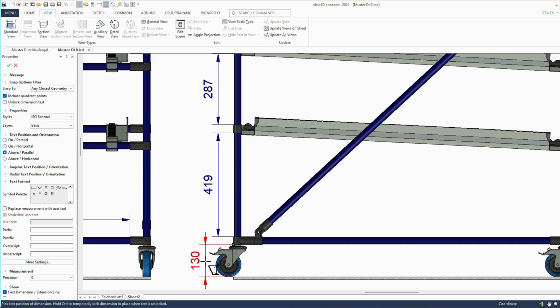It's important during assembly, when I clamp the joints onto the pipes here, I always make sure to clamp them only onto the outer surfaces and not onto the drive sleeve. When assembling, it's usually helpful to first just drive the drive sleeve into the pipes without fitting the wheels, and only when the assembly is almost complete can I fit the wheels in. That way, the frame is a bit sturdier without the wheels at the start, and only once the wheels are in place can I finish the frame, attach the roll rails, then the structure would already be finished during assembly.